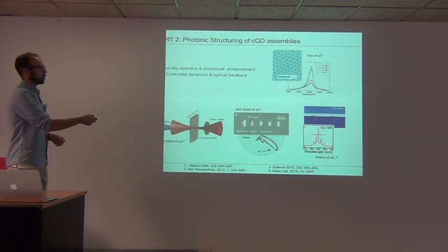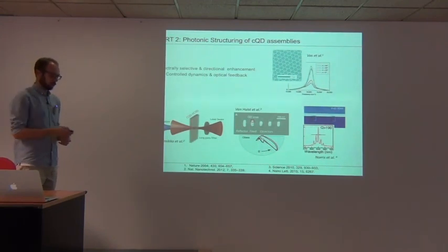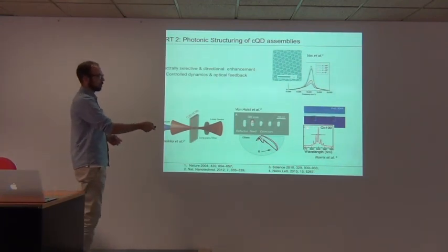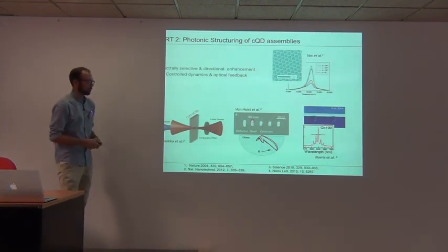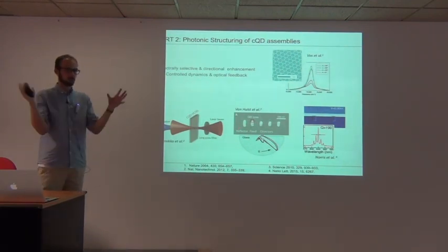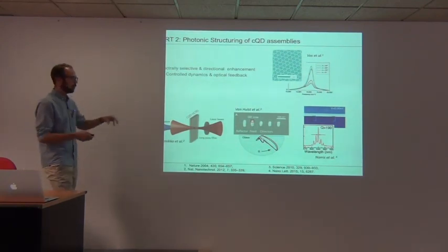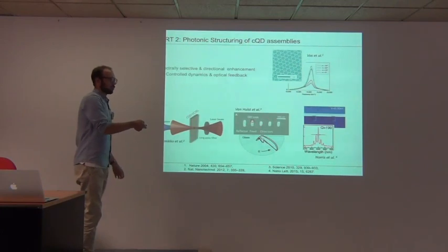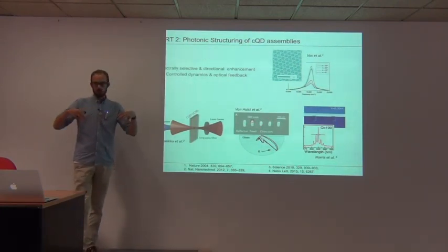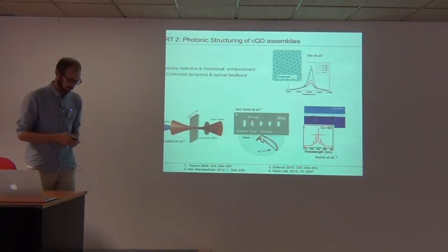Yagi-Uda antennas directionally couple the light out of these quantum dots, or plasmonics. There are also plasmonic cavities to really change the spectral shape, the dynamics and the directionality. So there are a lot of strategies available to take your quantum dot, couple it to an external structure, and control the directionality of outcoupling and those kinds of things.